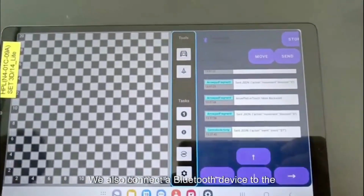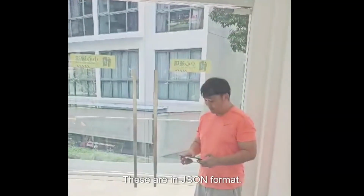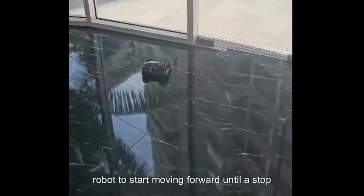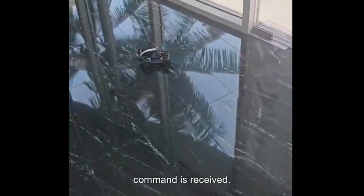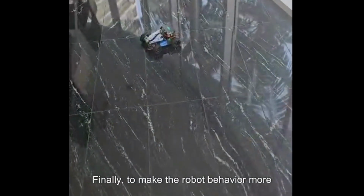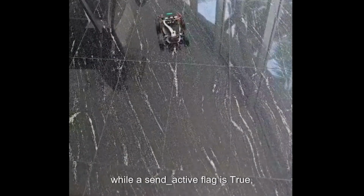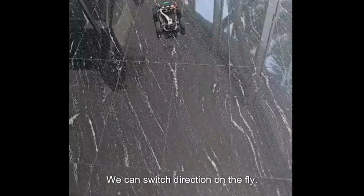We also connect a Bluetooth device to the RPi to receive user commands. These are in JSON format. For example, a command like action movement direction F tells the robot to start moving forward until a stop command is received. Finally, to make the robot behavior more natural, we implemented continuous movement using a background thread. This thread keeps sending movement packets while send active is true. We can switch direction on the fly.